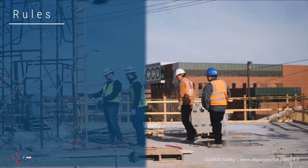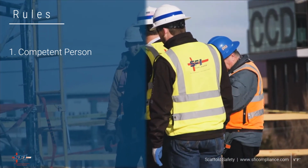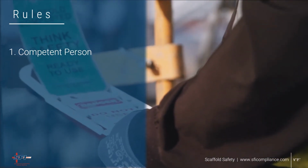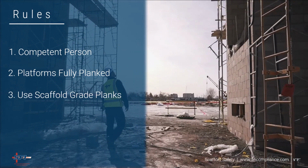Some rules to follow are: ensure a competent person is inspecting all scaffolds daily. The competent person should check guardrails, connectors, fasteners, footings, tie-ins, and bracing. Document scaffold inspections. Scaffold tags are great ways to document those inspections. Check to see that platforms are properly constructed and the platform is fully planked. Only scaffold-grade planks shall be used.